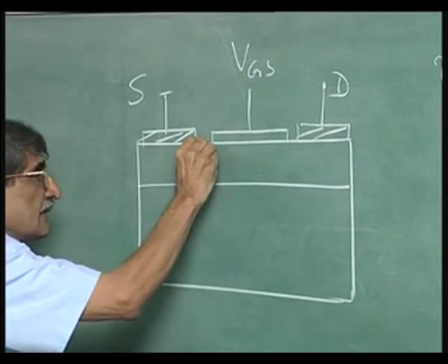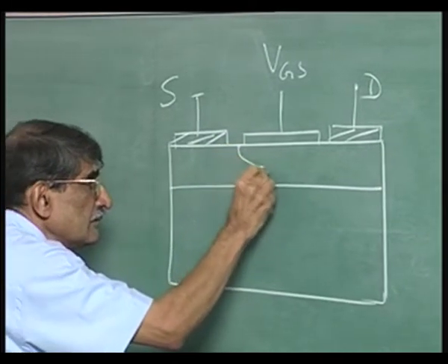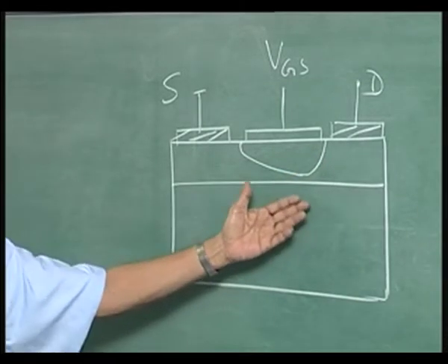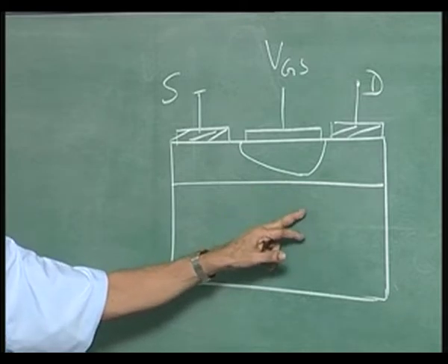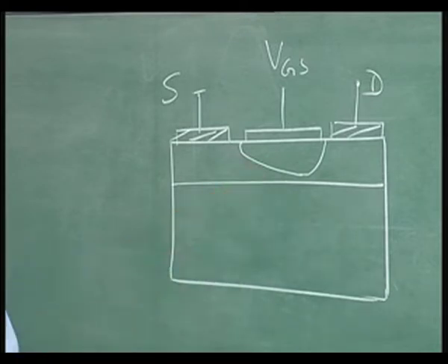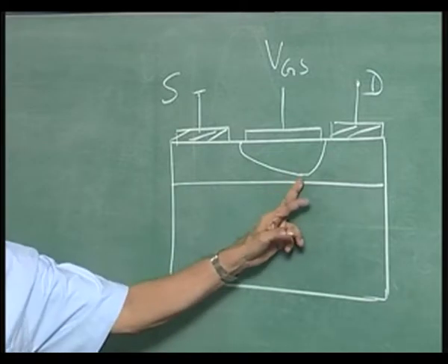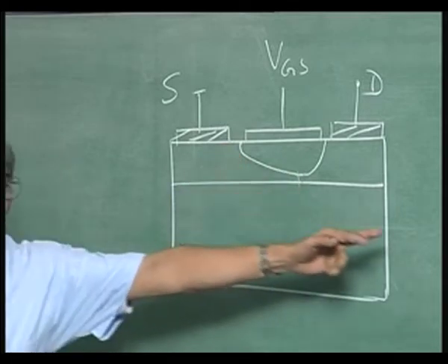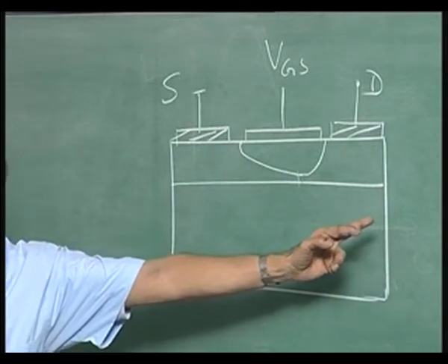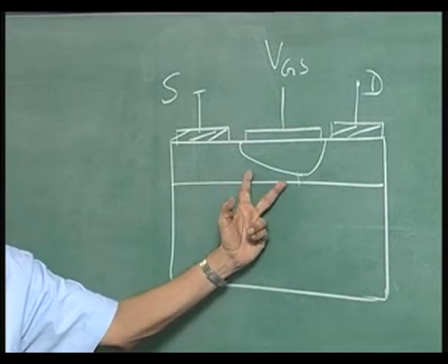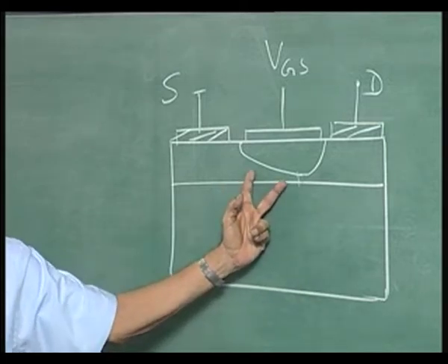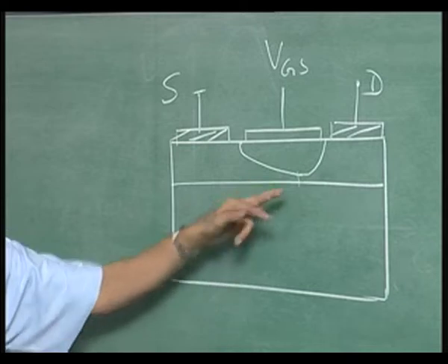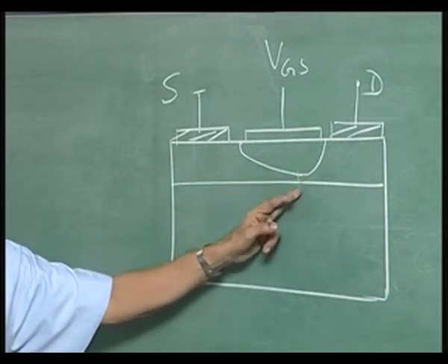So, what we are trying to say is, you have a depletion layer like that. It may or may not have pinched off. What we are saying is, for this condition that I have drawn here, velocity has saturated here, and beyond this point V is equal to mu n into E. That is what you are trying to point out. So, in this portion I write the same equations which we have used for Shockley's model, where V is equal to mu n into E. So, I get one equation for I d, and when the velocity is saturated here, the current is saturated.